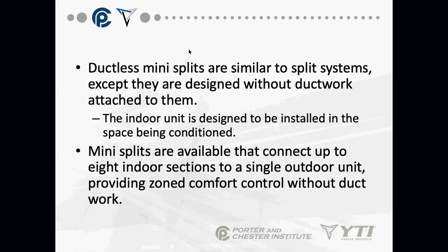All the line sets run to that outdoor unit, and it's all based on refrigerant flow and who is calling for heating or cooling at one time. Okay? Heating always takes priority over cooling. When you have multiple units, heating always takes priority over cooling.